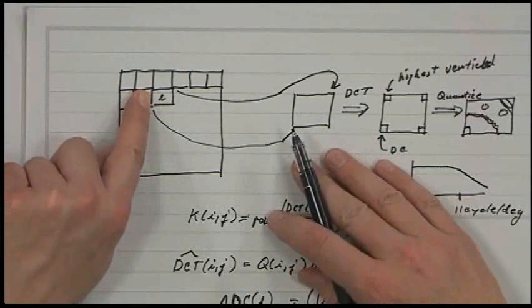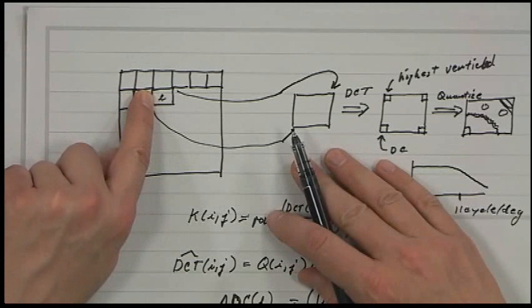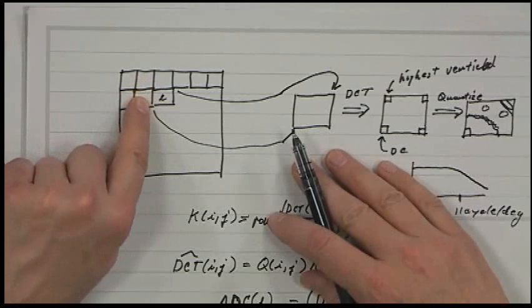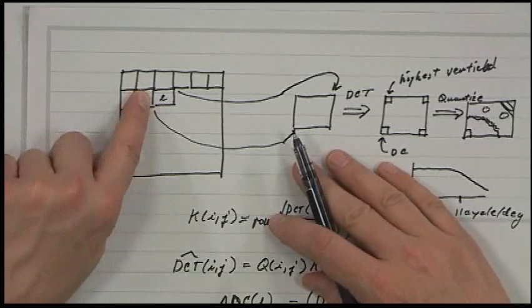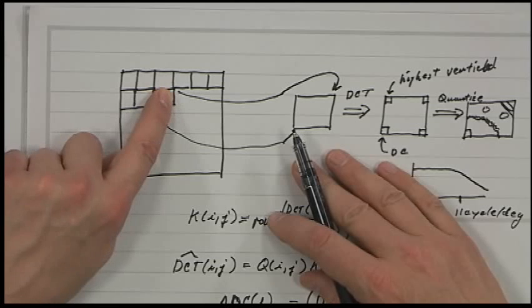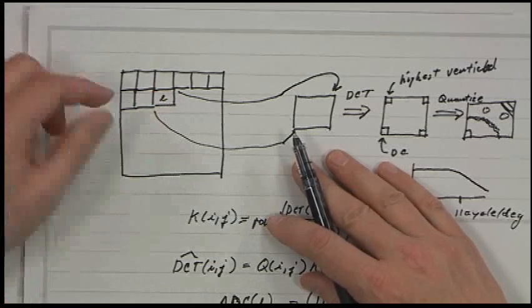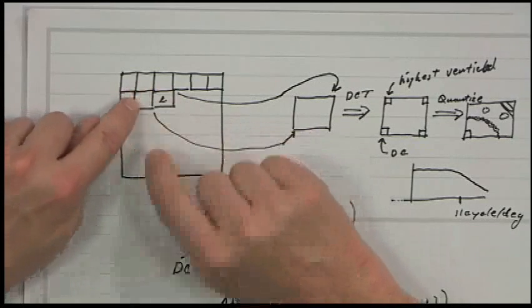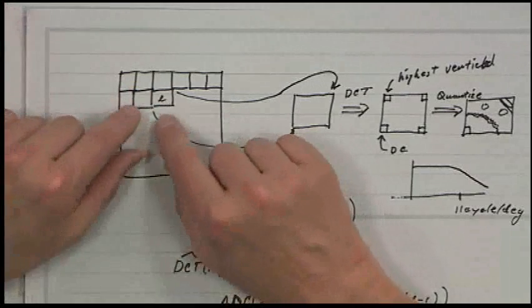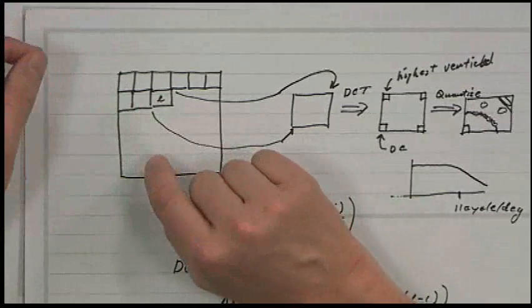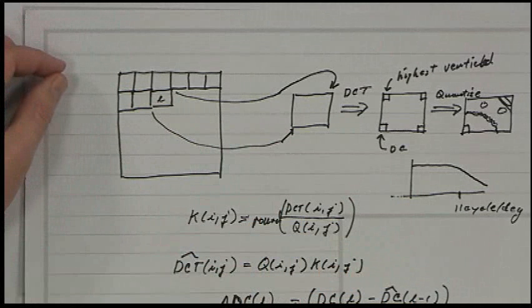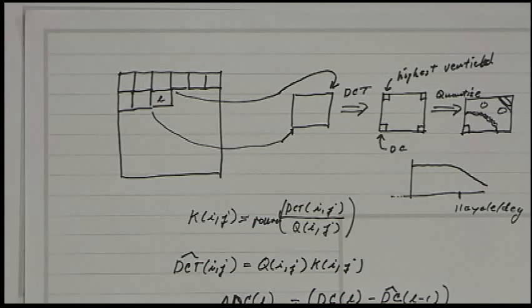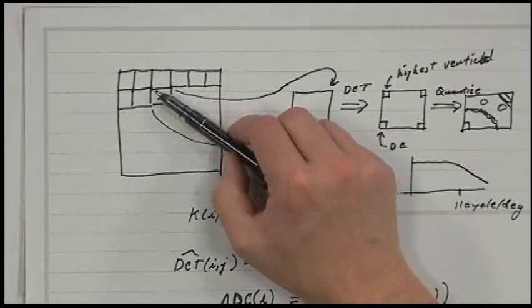Pixels on the edge of one block tell you something about pixels on the edge of the next, right? So you could have overlapping of the blocks, or you could decode this block and then use that to predict the pixels that you're going to code, and then just code the difference between the prediction and the actual values rather than code the whole thing. So there are a lot of things going on here that are non-ideal at the boundaries. Simple, plain old JPEG just ignores all the dependencies across the boundary, and you get blocking artifacts. There are more advanced JPEG block transform methods that do a better job of handling these redundancies.